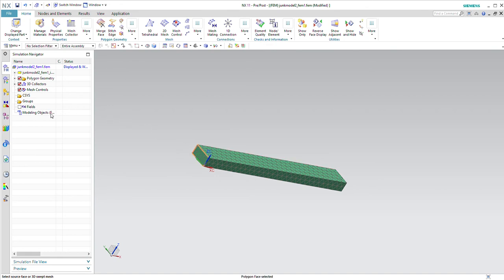and right now it's for an 8-noded element. So there's an 8-noded and a 20-noded. The 8-noded will give you a constant stress across the element, and the 20-noded will give you a variable stress, a linearly variable stress. You don't need as many of these 20s. So I'm going to try it with the 20 because I think I used the 8 last time I did this. And so let's try the 20.